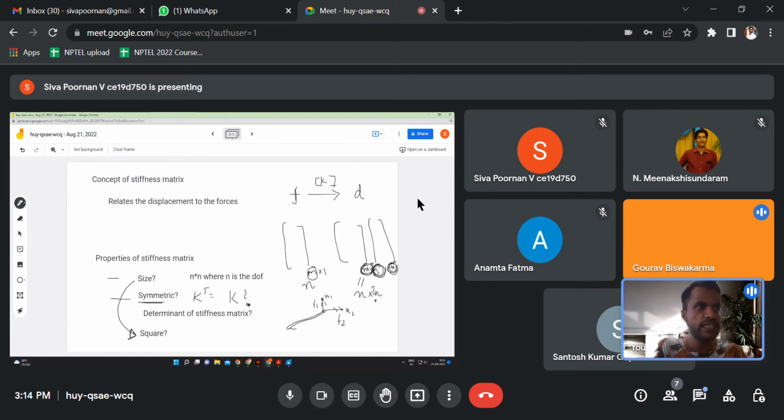So basically, you're saying that a force applied at point i, which creates a displacement at j, let's say it's dij, should be the same as the force applied at j and the displacement happening at i. Is it fine? This is what Maxwell's rule is, right? Betti's law also is. So that is one way to prove it. You can actually find out that it happens. How do you prove it? How do you show that that rule makes the stiffness matrix symmetric?